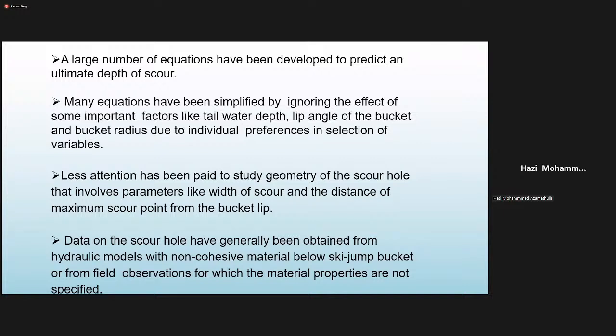Suppose someone is operating this, and something hits the tailwater; it won't affect it, meaning there is already tailwater depth. If you maintain some tailwater depth, sufficiently raising the water level on the downstream side, then whatever jet came, nowadays they are making a plunge pool, a pre-formed plunge pool. Another thing, the bucket radius is very, very important, but they have never considered it till now.